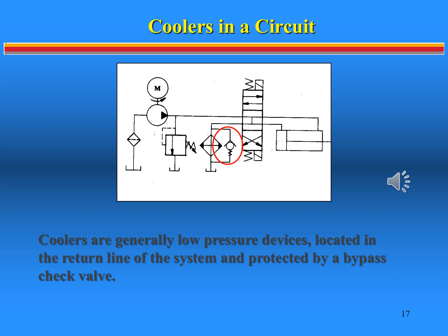The construction of most coolers requires that they be located in the return line to the reservoir. In addition to low pressure operation, they must be protected from clogging by use of a bypass check valve. The check valve ensures that oil flow to the reservoir will not be interrupted.